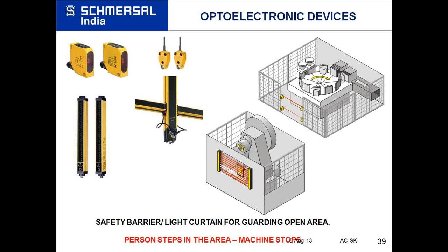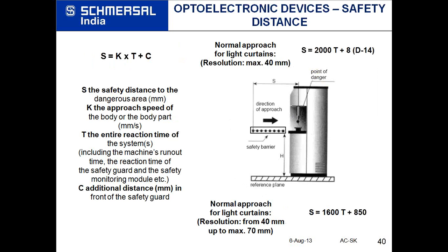So there is a formula for calculating safety distance. Okay, and this safety distance is calculated in millimeters, and you can see the formula is different for different resolutions of light curtains.